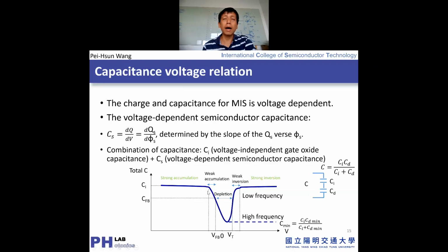The accumulation is only determined by the doping concentration. So there is not enough charge to be modified. So you can see that under flat band condition, we get slightly lower capacitance in comparison with the strong accumulation. And furthermore, if you consider the depletion region with the voltage on the other side, you can think that there is a flat band voltage in between 0 and the flat band voltage. The reason is because we have a metal, and the work function differs between the metal and the semiconductor. So since there's a difference, we need to use the flat band voltage.